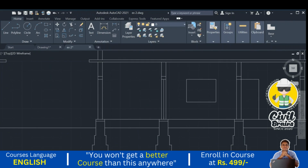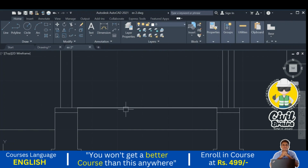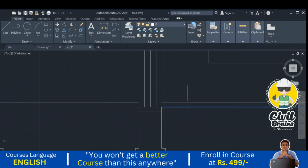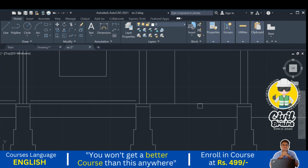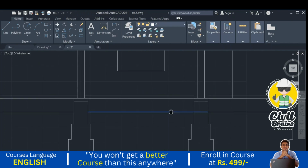Next, flooring. We have not shown the floors. Flooring will come above the PCC plinth level. What is the thickness of the floor? We can consider including the sand bed and include the thickness of the floor. I am considering 0.1 meter. 0.1 meter is more only. Normally it is between 0.05 to 0.1.